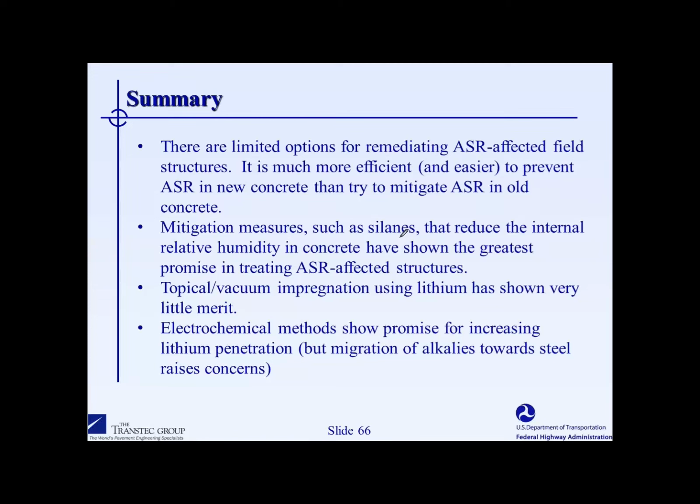In general, what we found is that the methods that reduce the internal relative humidity tended to be the most effective, but again, we know that these type products have limitations. We don't know if they'll be effective with regard to, say, treating a pavement or an abutment where you have water coming from the backside, but we'll hope to gather enough data to answer that question.